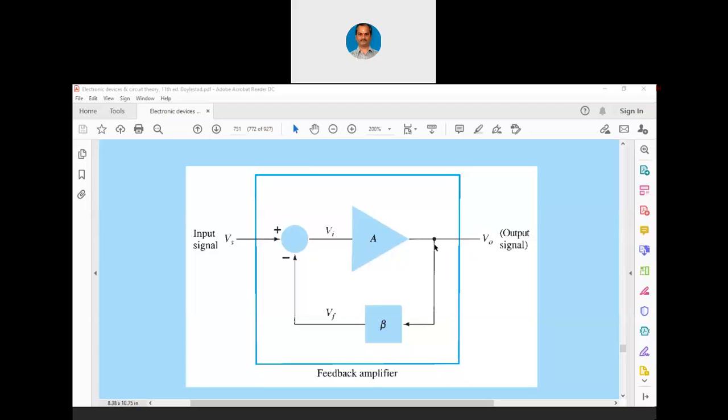Generally, we engineers use a lot of symbols in our professional lives, and each symbol has a distinct meaning. If the output impedance has to be ideally 0, or practically very low, it simply means that whatever load we connect at the output, the amplifier must be able to supply that much energy or power to the load. From where will the amplifier derive all this energy? Obviously, from the power supply itself. That is why the amplifier symbol is a triangle.